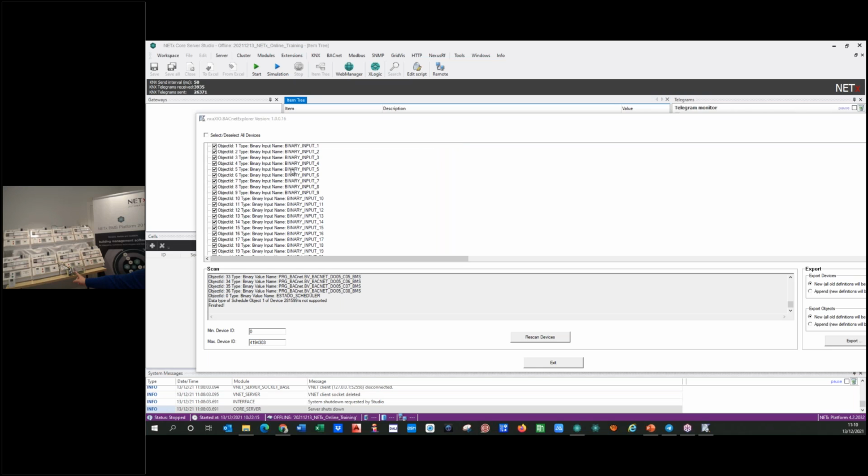On the screen, you can see the binary inputs and binary outputs, but these outputs are not the right ones, because it's necessary here to create specific output blocks. Well, it's a question of the PLC, because these outputs are not possible to control through BACnet, so it's not interesting to import them. We can save and select this here, or we can do it, of course, after importing if you want.